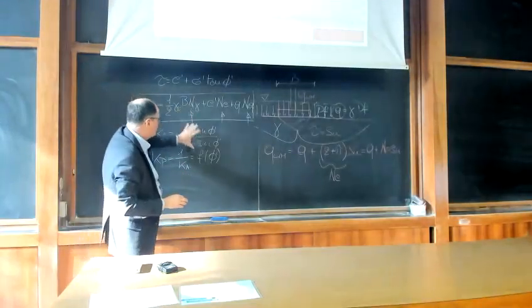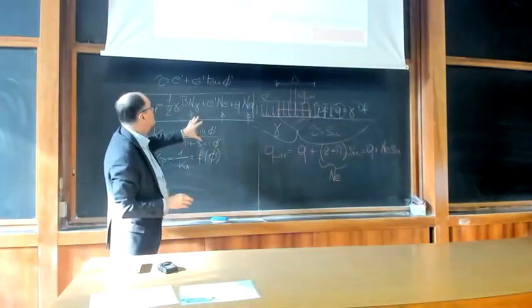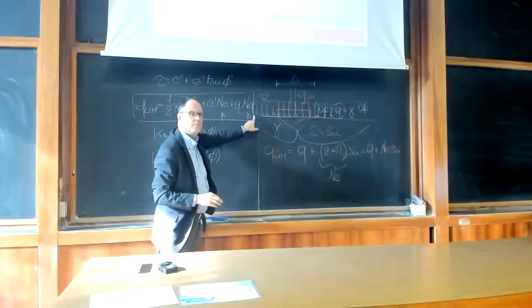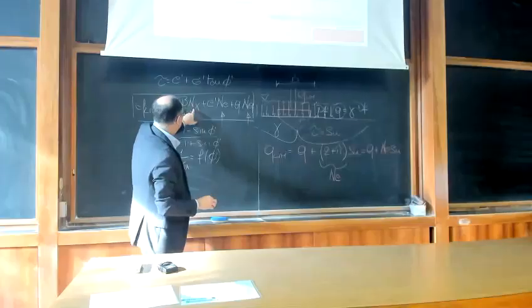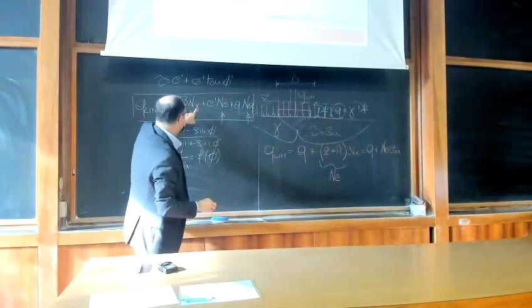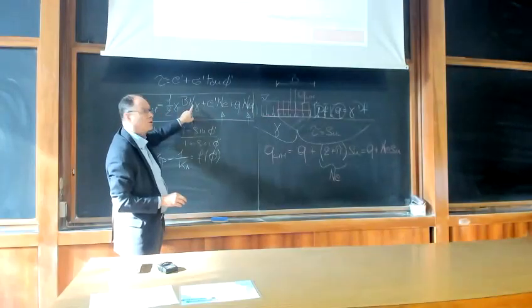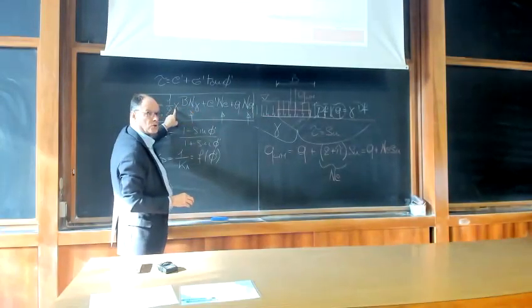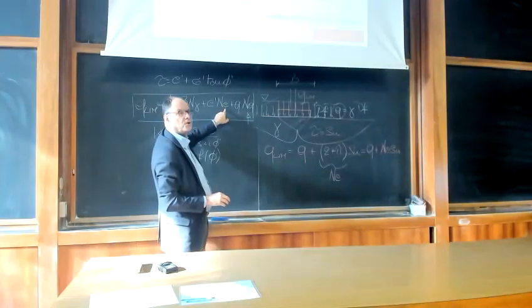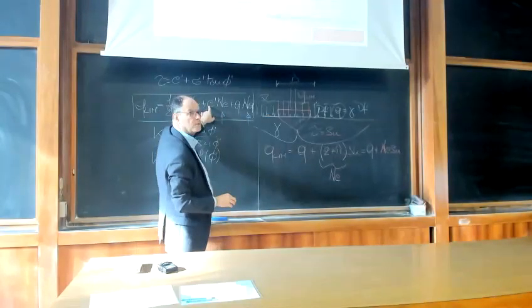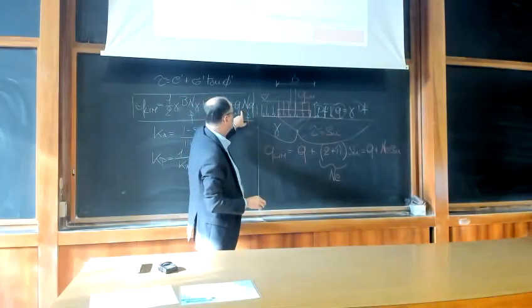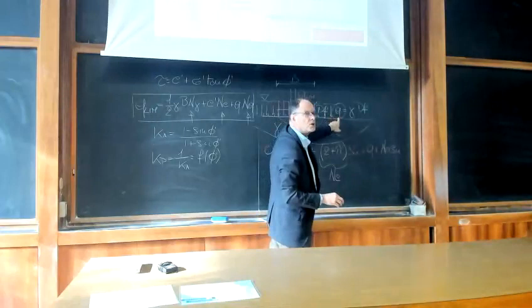So, of course, phi is the main parameter, and phi provides you with the expressions of N gamma, N C, and N q. Now, the subscripts gamma, c, q refer to the fact that this is the bearing capacity factor which refers to the soil weight, gamma. This is the bearing capacity factor which refers to the cohesion, C prime. This is the bearing capacity factor which refers to the overburden pressure, this q.